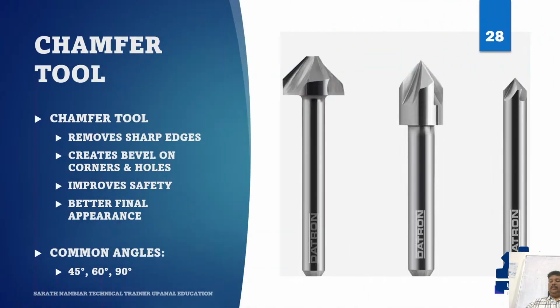Next is a chamfer tool. It is a small tool that creates a big professional difference. After roughing, finishing, drilling, and profiling, many components still have sharp edges. These sharp edges may look unfinished. They may cut operators' hands. They may create burr problems during assembly. That is where chamfer tools become important.